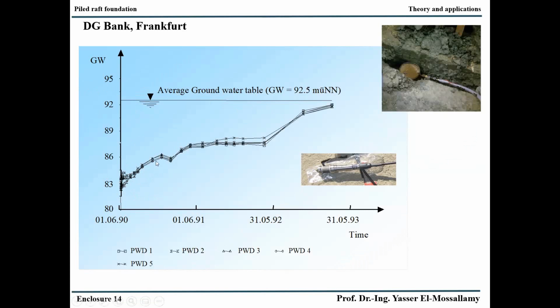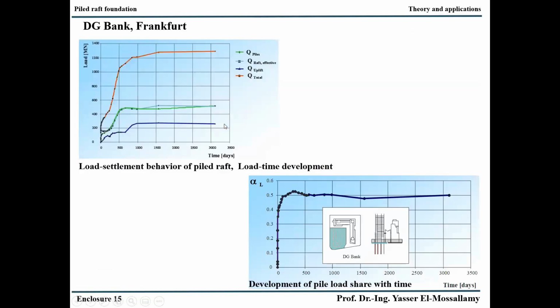And when we finish the construction of the basement and start the construction of the high-rise building, with time we reduce the amount of dewatering till we close the dewatering and we come again to the hydrostatic pressure. From all these measurements, we can see how much load is taken by the piles, how much load is taken by the raft, the uplift, and the total load of the superstructure.